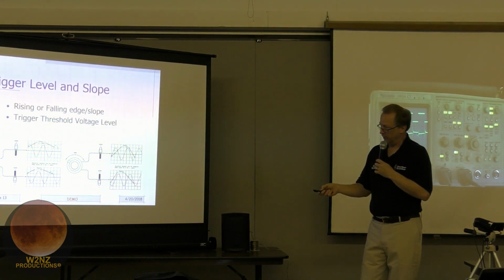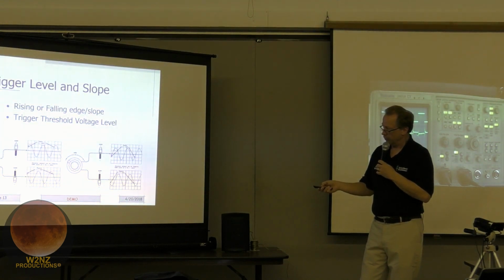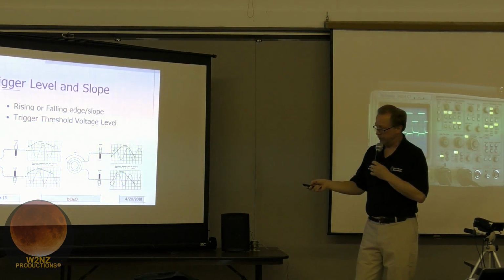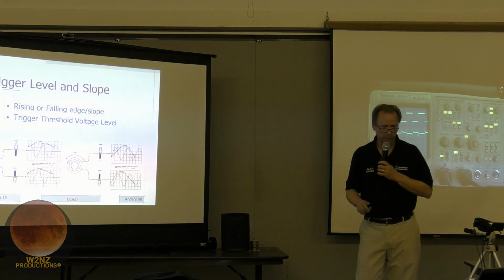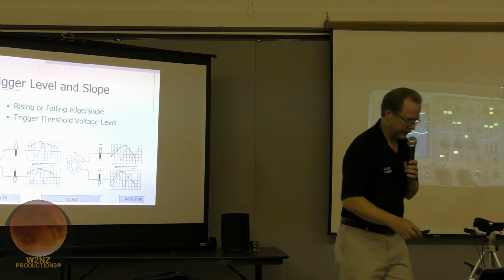So with it adjusted a little bit positive here, we can see we're starting a little bit above the baseline, where this knob is turned a little toward the negative, so we're starting the waveform down here. So that's where our threshold is. If the threshold is here, I'm going to trigger on a positive slope coming through that threshold. That's why the signal's starting right there. Okay? In fact, a good way to look at this, let me see.